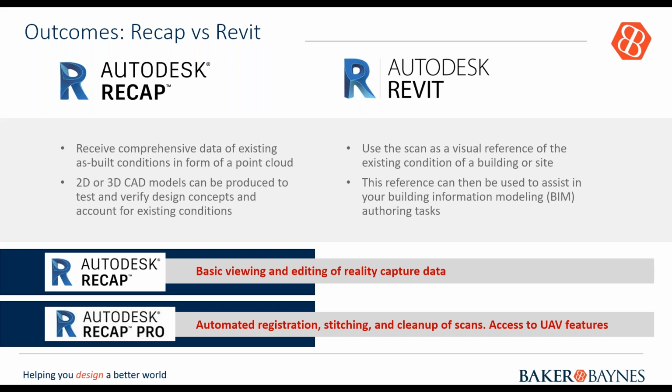In Revit specifically, we could then import that Recap file or the point cloud file and use this as our shell if we had an existing environment or building that we wanted to reference. We can use that as a reference and then build on top of that. We can also do things like measure within Revit to give us certain bits of information that we might need.